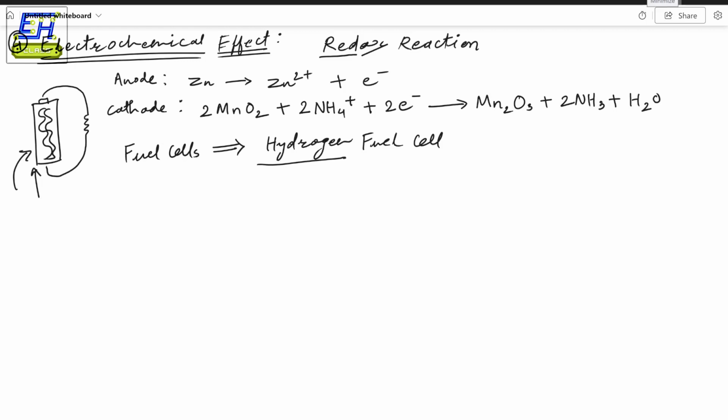And if we come to the math, if you really would like to go into the depths, the voltage formula, the EMF formula for the cell actually comes from the Nernst equation, but researchers have narrowed down and made standard equations for calculations in a standard environment, right? So in that, you simply need two variables. If you would like to calculate the EMF of the cell or the open circuit voltage, that is the standard potential of cathode minus the standard potential of anode.